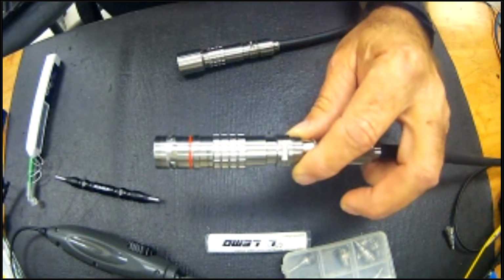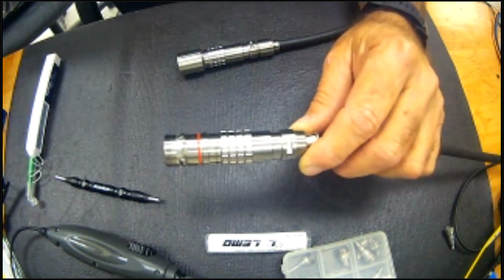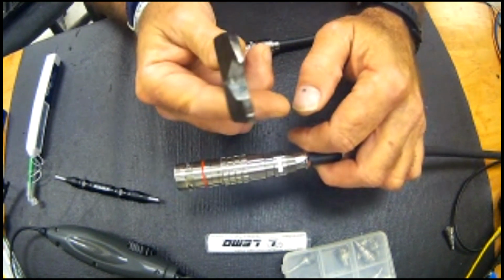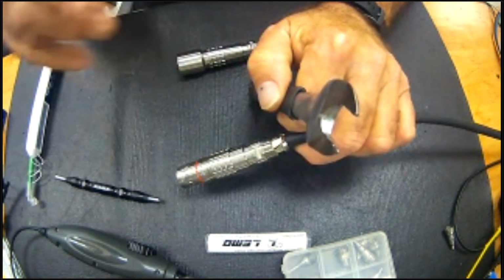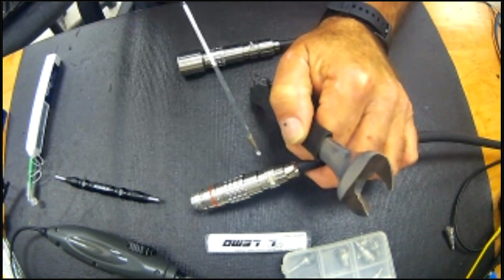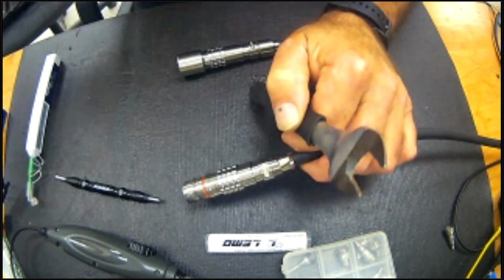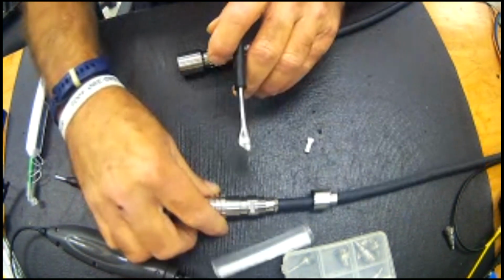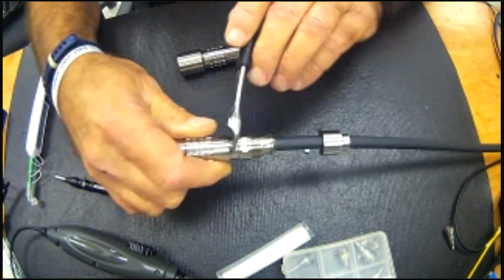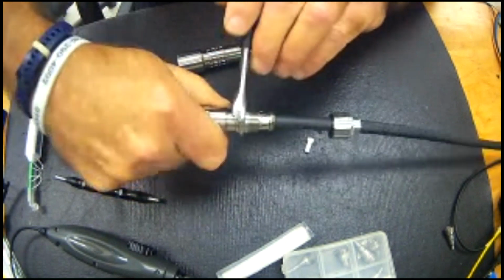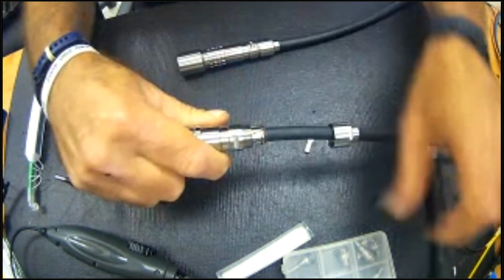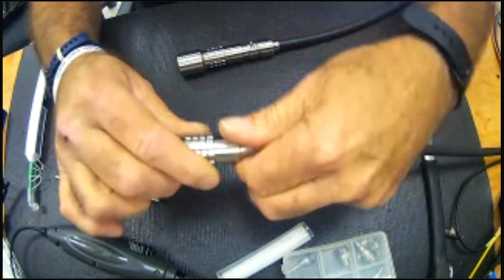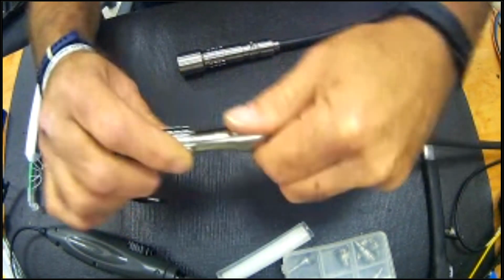In order for you to properly disassemble this connector, you need a very, very thin 15 millimeter wrench. These have been ground down. You can purchase very, very thin wrenches on the web, or you could grind your own down, 15 millimeters. Now basically, back this up, and they're always going to be Loctite. So expect to find a little bit of Loctite, preferably blue. It is a steel-on-steel connection, no set screws.